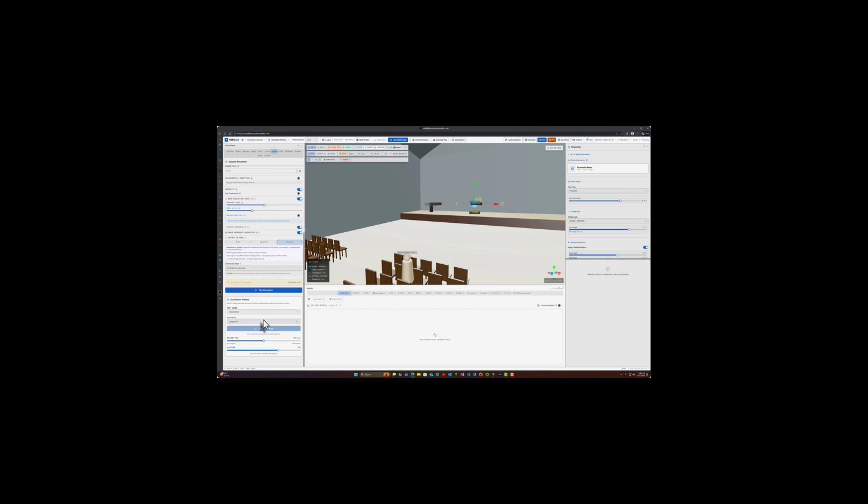We're in the home stretch. Before we can enter live walkthrough, we need to choose probe spacing and bake the probes. In NEBULAB, probes are sampling locations throughout the space where impulse responses are computed. During walkthroughs and flythroughs, NEBULAB interpolates between nearby probes to create a smooth, continuous acoustic experience as you move.